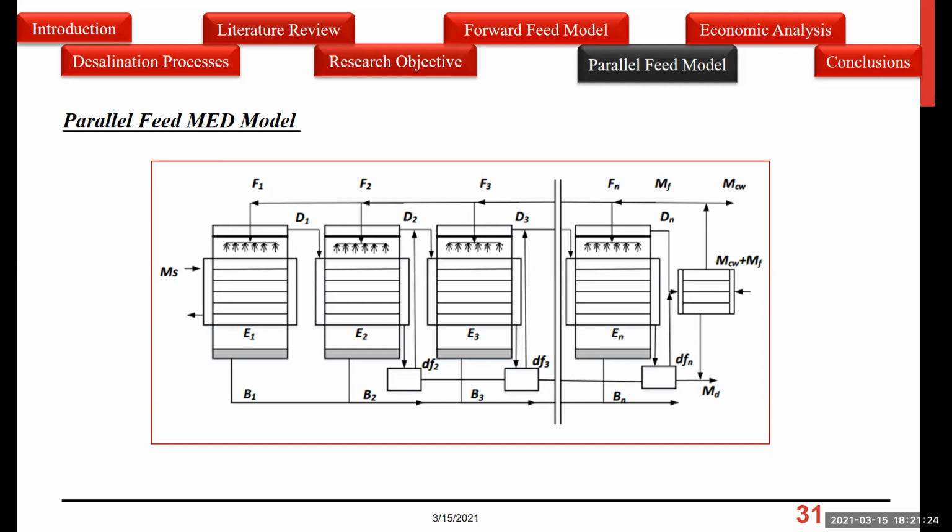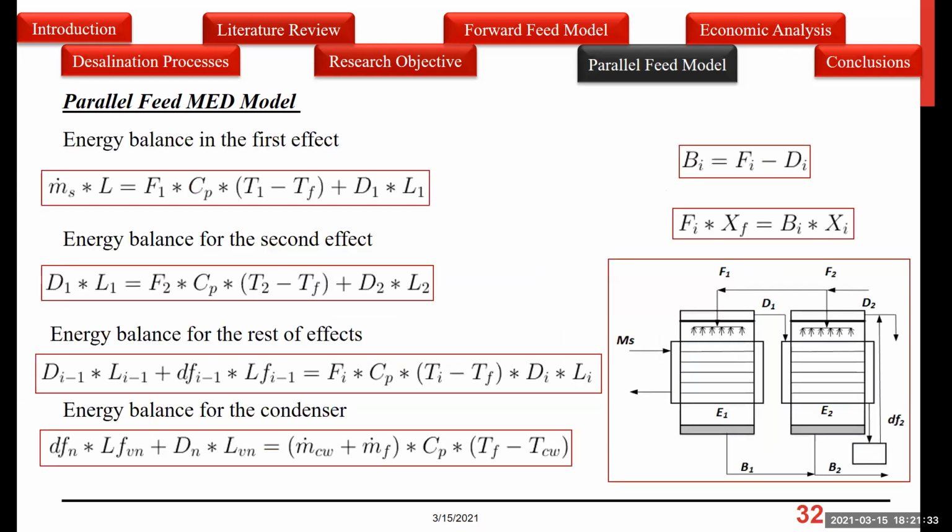And the thermodynamic analysis that has been done earlier can be done for this unit, just to see the unit as operating as a parallel feed MED system, putting the energy balance equation for the parallel feed system. And because it's parallel, again, I need to remind you that for each one of the effects, there is sensible heating of the water which is being sprayed, and then latent heat.